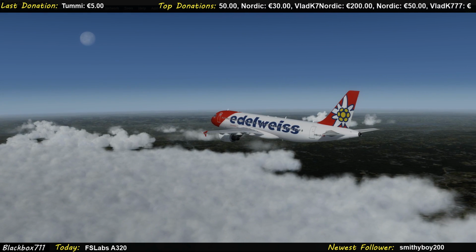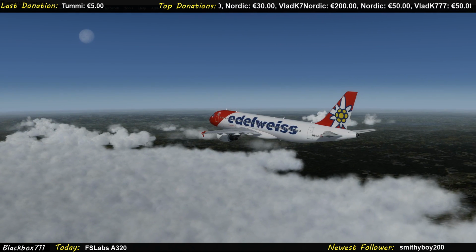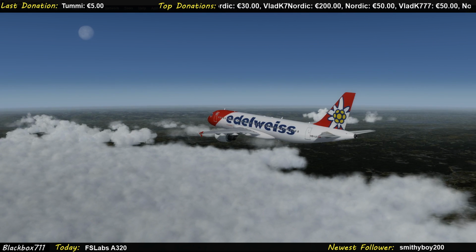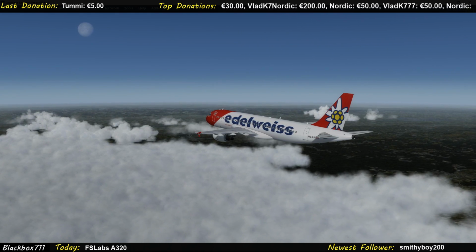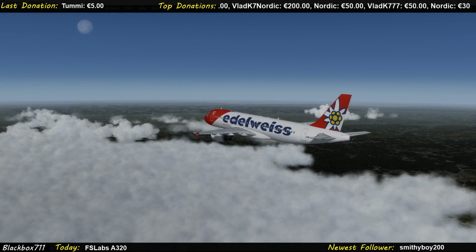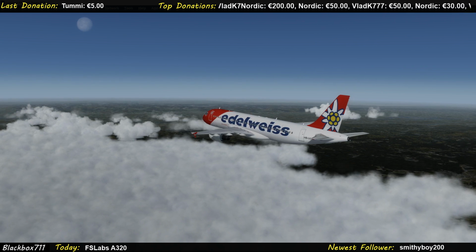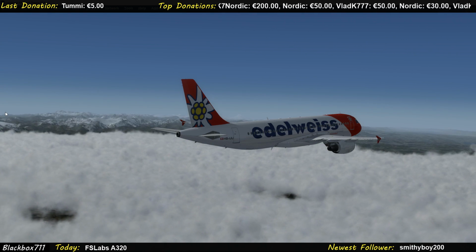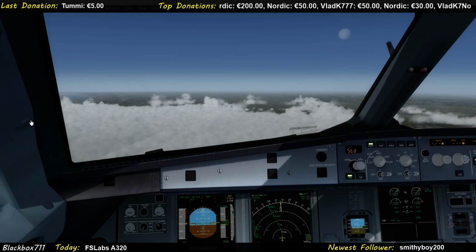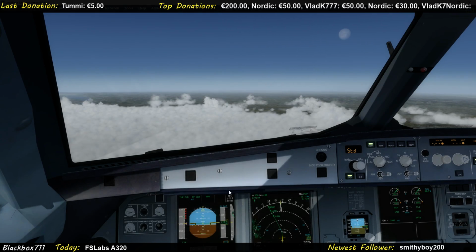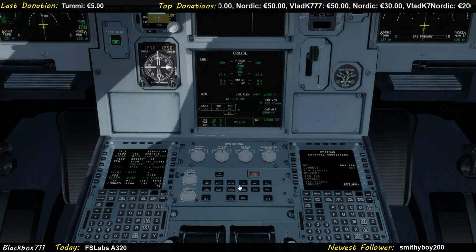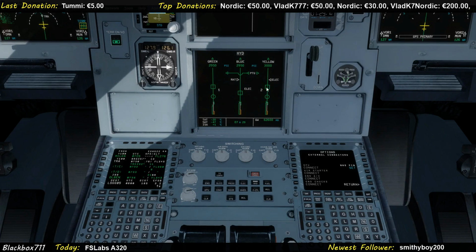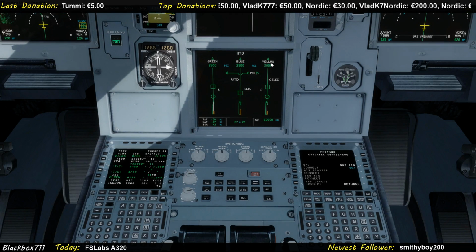With dual engine failure, can you extend flaps? Well, it's one of the trick questions. It depends if you have windmilling in the engines, i.e. if it's enough windmilling in the engines, then you would have the possibility for the yellow and green engine-driven pump to still supply sufficient power to the hydraulic systems.